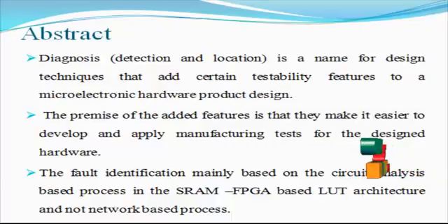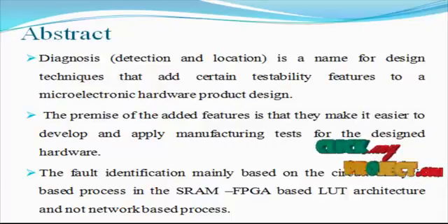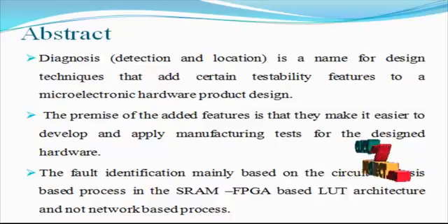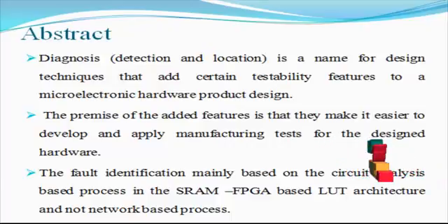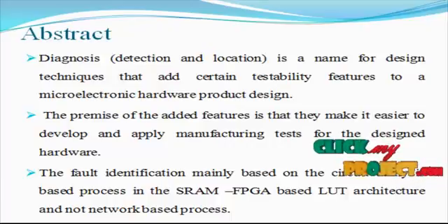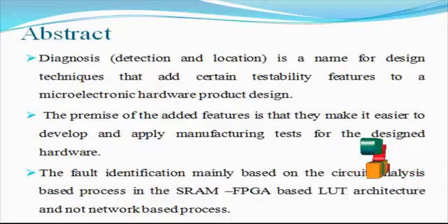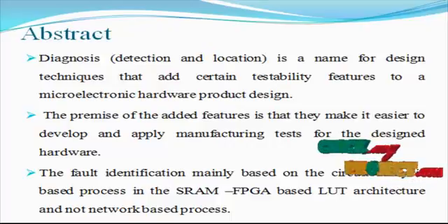Currently, the programmable interconnect accounts for more than 80% of FPGA programmable resources. Therefore, the nets in the interconnect resources are very vulnerable to faults, both in the manufacturing as well as the runtime process. For interconnect resources, FPGA testing methodologies are broadly classified as application independent and application dependent. Application independent testing is also known as manufacturing based testing, while application dependent testing utilizes the specific design implementation of the FPGA.